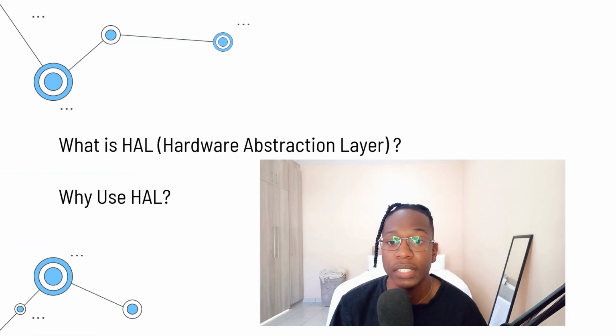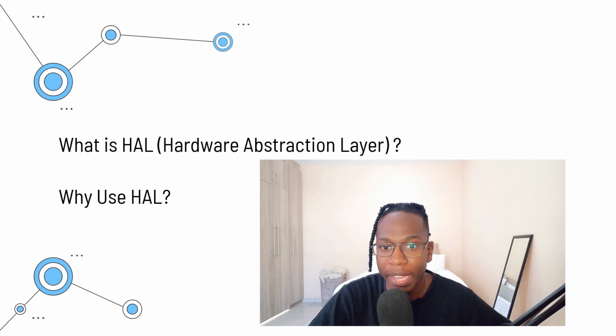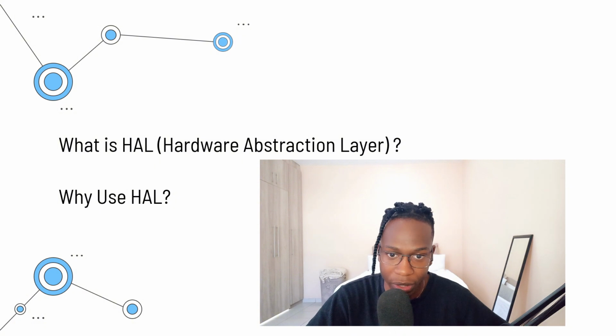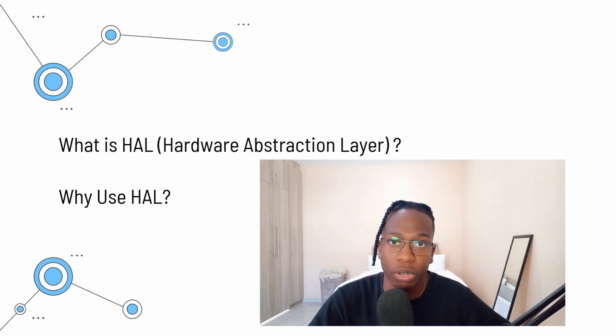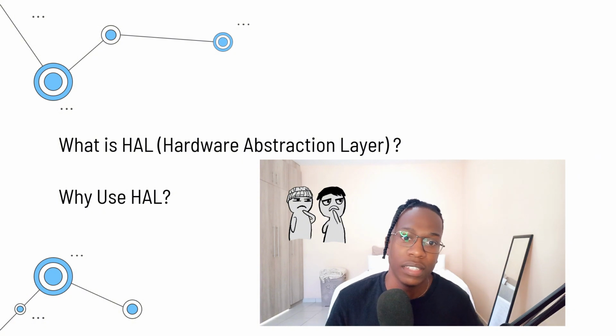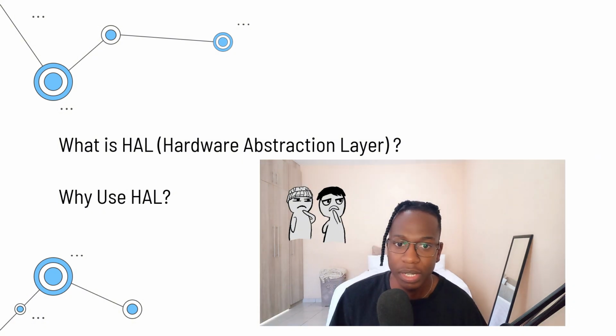Before we can actually start coding, let's talk about hardware abstraction layer, HAL. So HAL is a library provided by ST Microelectronics that simplifies the process of configuring and controlling the STM32 peripherals. It basically provides a set of functions that allow you to interact with the hardware without actually having to directly manipulate the microcontroller's registers. A question you might ask is, why should you use HAL?